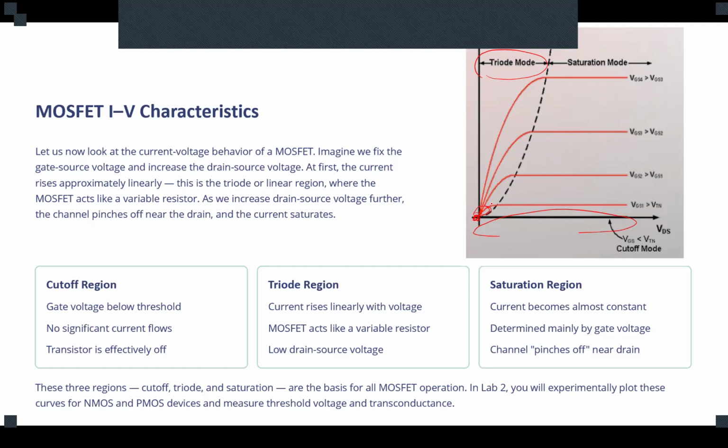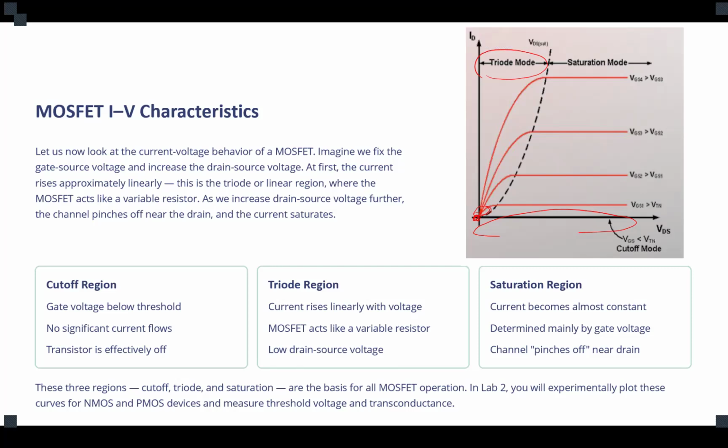Now, you can see that this is not exactly linear, but similar to the diode that we talked about with the constant voltage drop model, we can assume it's linear and ignore that exponential-like knee on the curve. Is that clear? Are we good on that?